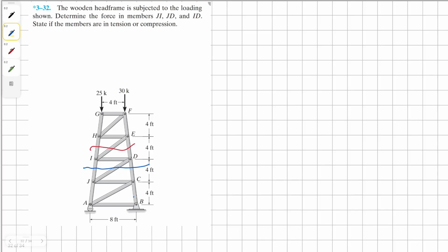Before we even begin, let's find our angle here. We're going to call it angle theta. To find angle theta, we know that our top member GF is 4 feet and our bottommost is 8 feet wide. So therefore the difference is 4 feet. And to get the difference on one side, either on G or F, we have to divide it by 2, and we know that's because this structure is symmetrical. So that means each side has an extension of 2 feet.